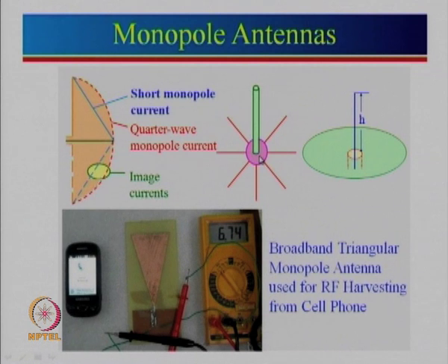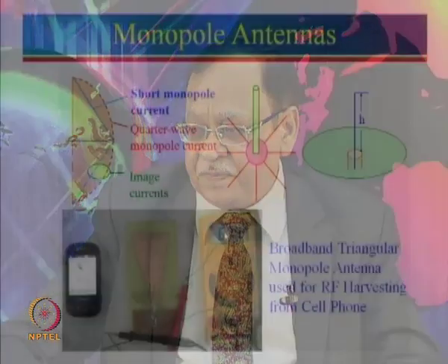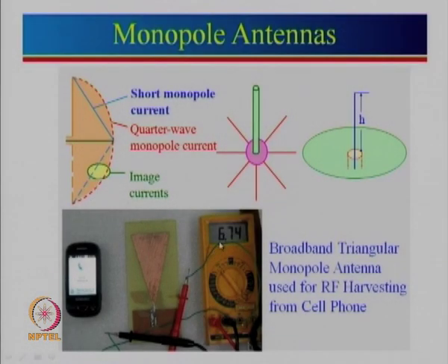In fact, for medium wave transmission, which I mentioned in the last lecture, medium wave transmitter at 1 megahertz would require an antenna of the height of 75 meter, and there we need to provide a ground plane. Now, earth may not be always a perfect ground plane, so lot of these radial lines are put on the ground, and these are long radial lines which have to be put. So, they will actually simulate the real ground plane. We have actually shown here one practical example also.